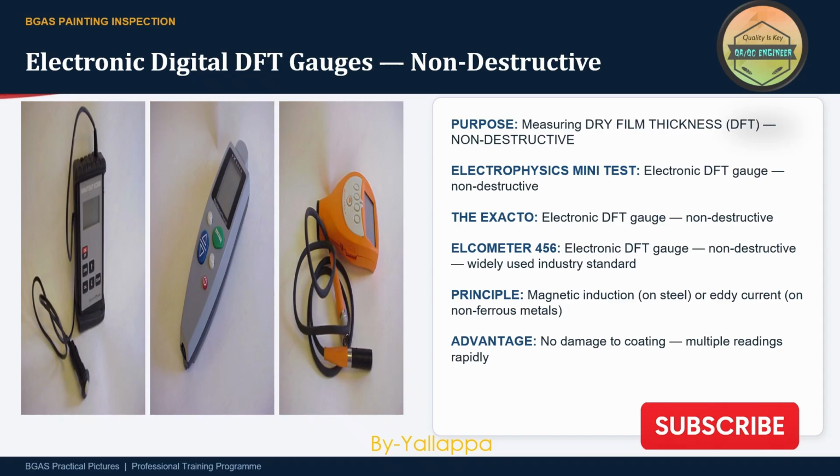Before measurements are taken, calibration and verification must be performed using certified standards. Remember: calibration first, measurement second, acceptance decision third.